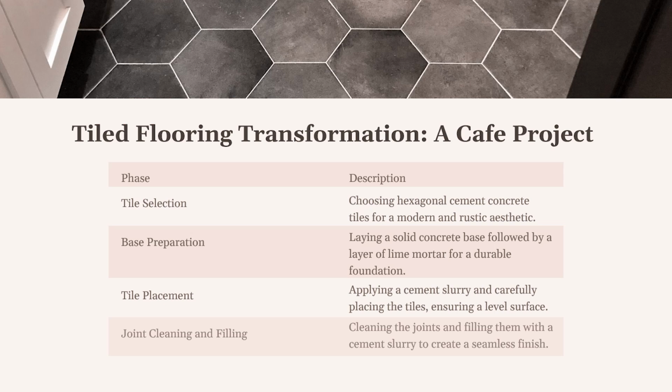And the next day, we clean the joints between the tiles using a wire brush and fill them with a cement slurry of the same color as the tiles. After curing the floor for 7 days, it is ready for grinding and polishing, much like terrazzo flooring, to achieve a smooth polished finish. The result, a stunning, durable tile floor that adds character and charm to our Bangalore cafe, ready to welcome customers with its fresh new look.